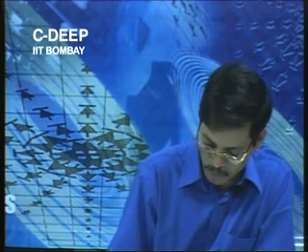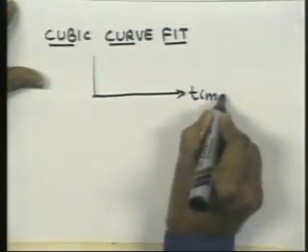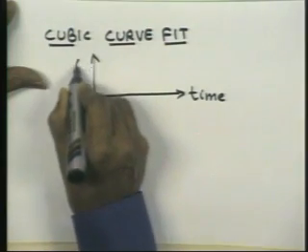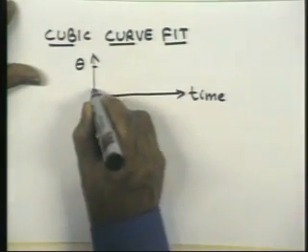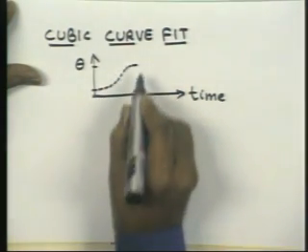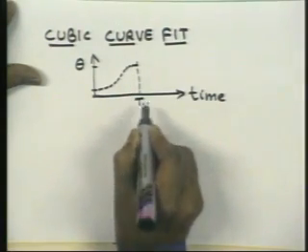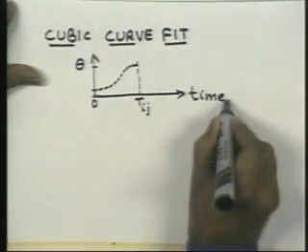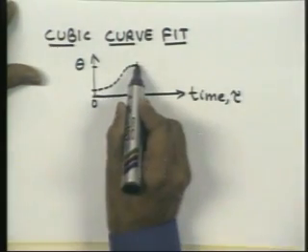So, if you look at, for example, this type of a cubic spline strategy, the typical position variation with respect to time could be something like this. Okay. This is Tij, this is 0, time tau in the local coordinate frame between theta I and theta j.